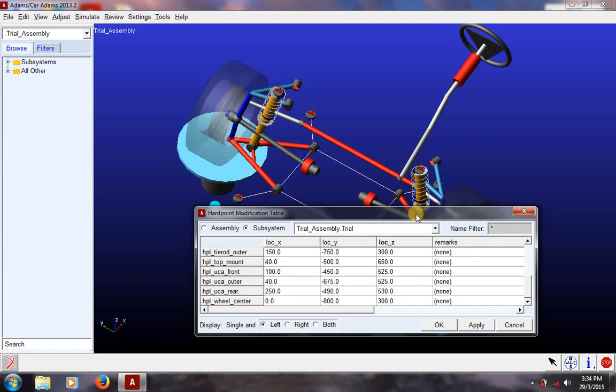So now here comes, suppose we want to make a double parallel wishbone. So to make such, the distance between these two and the distance between these two should be the same. So let's go and verify the front and the rear. Y is given as 300, minus 300, X is minus 200, 200. So I would set it the same way, 200, 200. Mind you, this is just a demonstration of the capabilities.